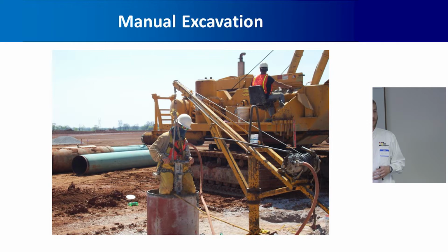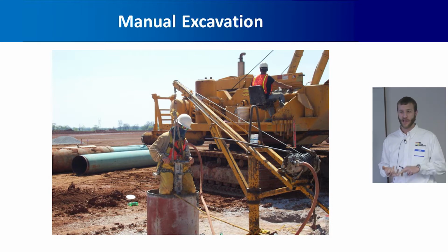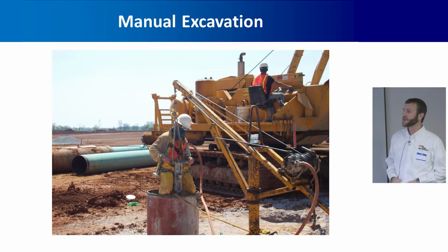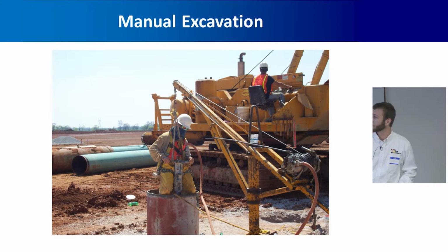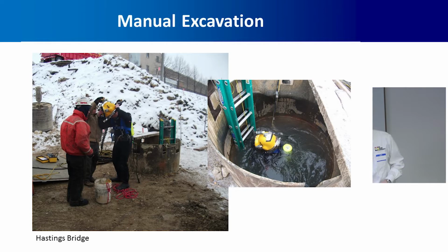Not so common anymore, but manual excavation. This is not allowed in a lot of places, but it is allowed in some places. Some states, particularly in the southeast, it's common for dry holes to send the inspector down the hole. You would only really do that if you've got a cased excavation or a stable rock socket. You wouldn't send somebody down just a clay shaft that's standing up on its own, but not completely unheard of these days. Don't do it.